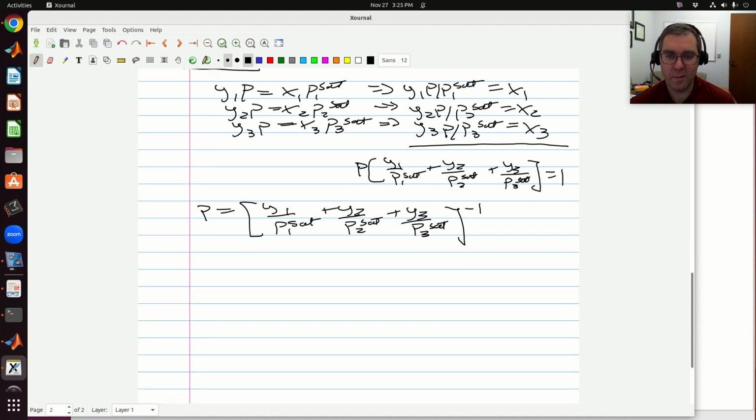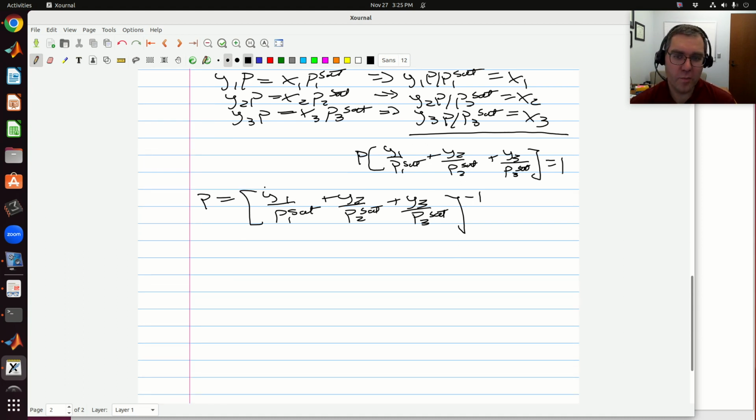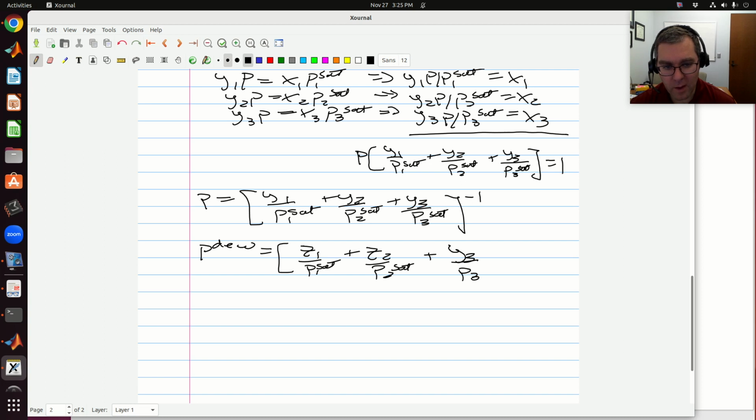Okay, or to make it complete, at my dew point, my y's are equal to my z's. So I end up with P dew is equal to z1 divided by P1 sat plus z2 divided by P2 sat plus z3 divided by P3 sat. Here, y3 is z3. Okay, I'm going to box that in.